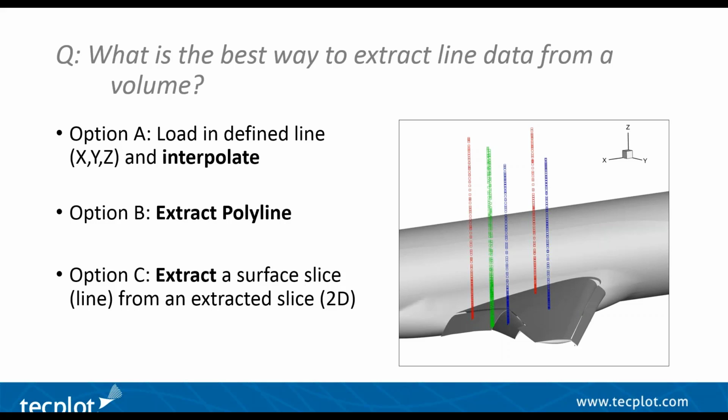So the extracted lines from one model, you can export those to a data set and then load them into another data set and have the exact same points for every single model. And this could be useful if you're looking to compare the lines between model to model, as the extraction locations will be identical between the two methods.